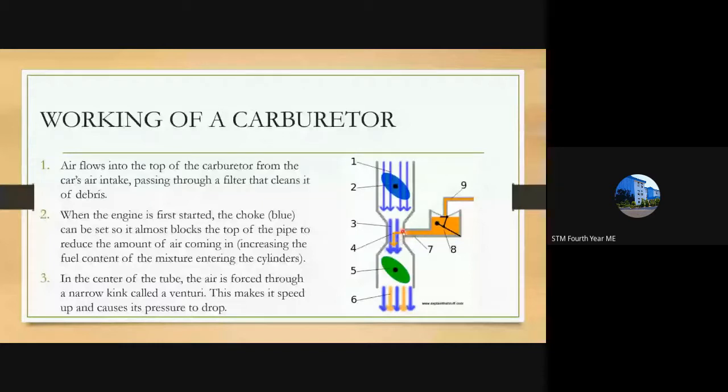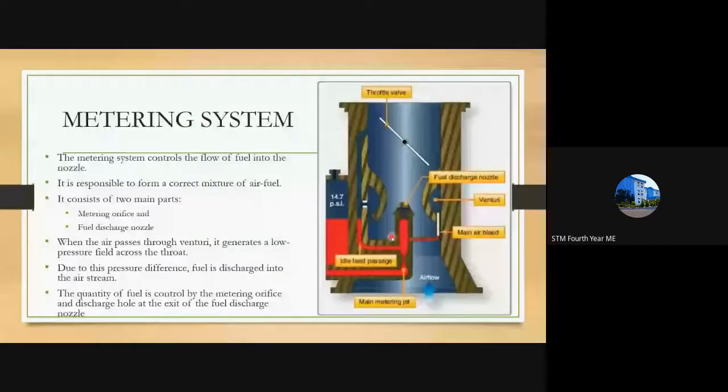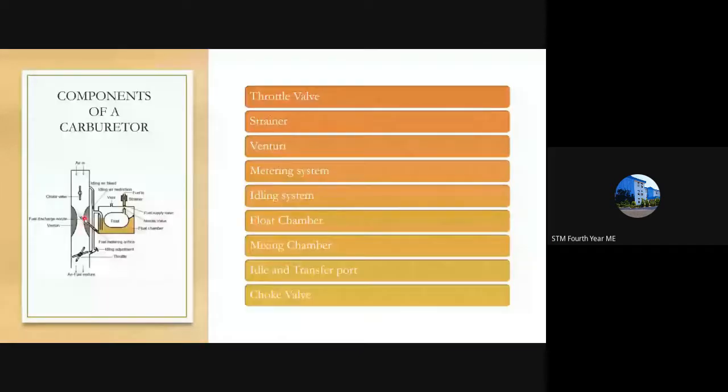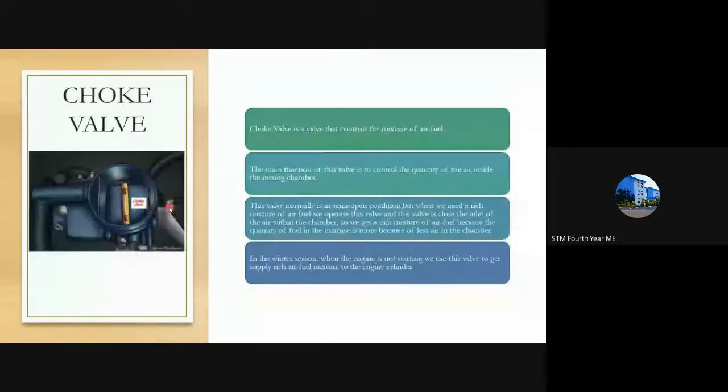When this happens, the fuel will be sprayed here. The fuel will escape through here through a nozzle, which you can see. Here you can see the nozzle here also. And in the schematic diagram, you can see how the fuel is escaping here. You can see a few droplets of fuel. So that will be mixing with the air at the venturi. So that is how fuel is escaping from that point.